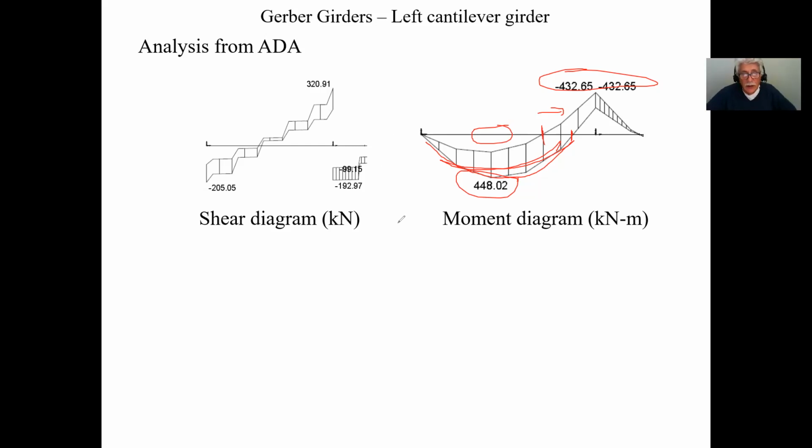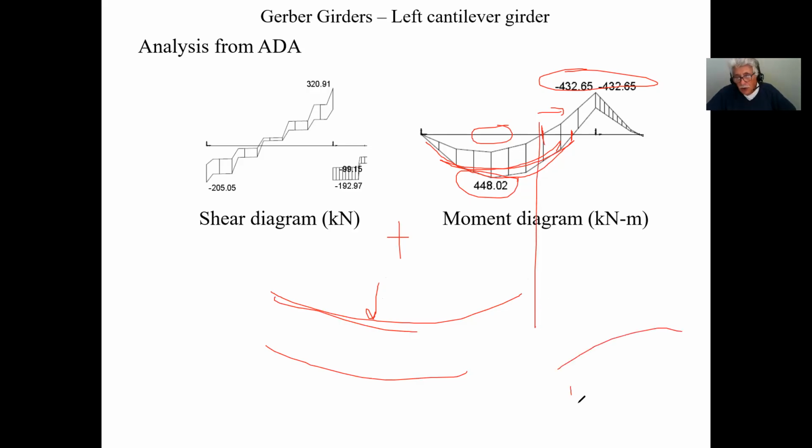In other words, when we say we have a positive moment, that means that the top flange is in compression, okay? And what happens here is that at this point here, the bottom flange goes into compression. And unfortunately, because our joists are only supporting the top flange, this becomes unsupported. And therefore, our LU becomes the full span. You see, and that's what people don't realize.